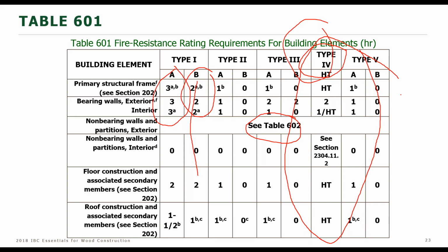And in that way, if you watched any of our new mass timber presentations and the webinars we already have online, you'll see that the goal for fire performance in the new mass timber construction types is to allow a building content fire to burn out without it affecting the structure of the building. So you have in your taller mass timber buildings the potential for a contents fire to start.